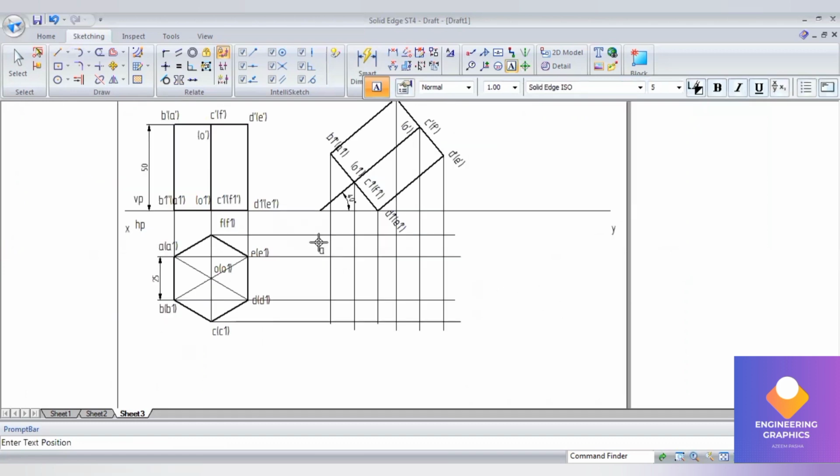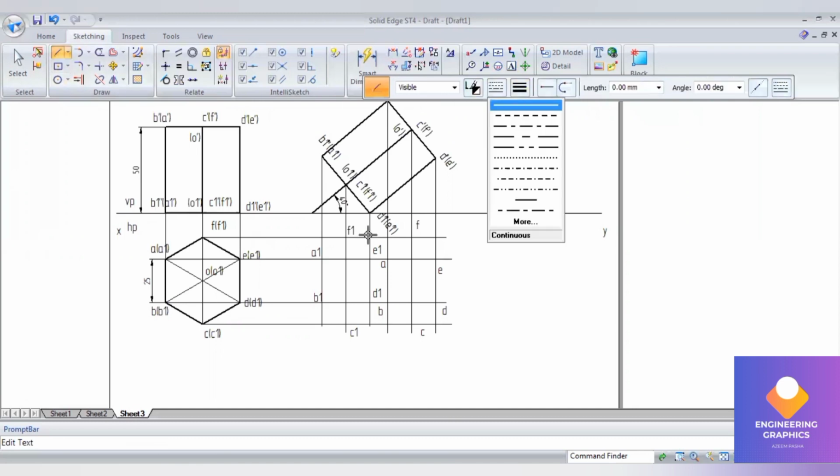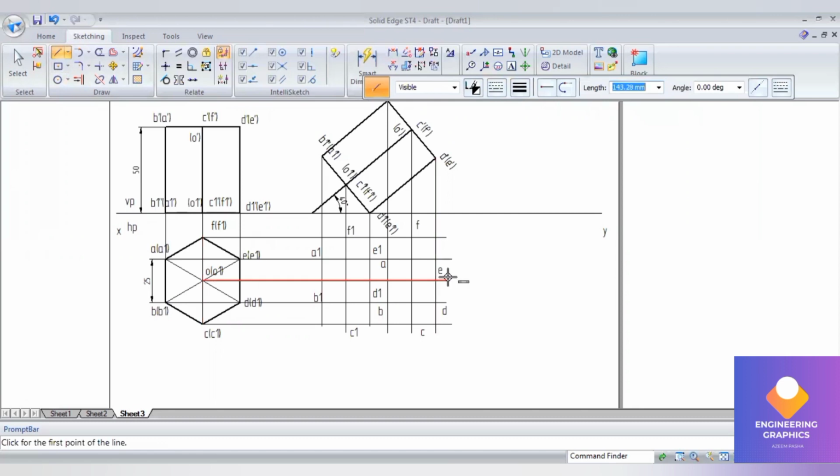You can see clearly here we get the bottom face notations. You write them down as A1, B1, C1, D1, E1 and F1. Okay, and here we get the top face notations. You can mention A, B, C, D, E, F. And now we have to draw another projection line from the center of the axis. Yes, from this end draw projection lines, and here this is O1 and this is O.